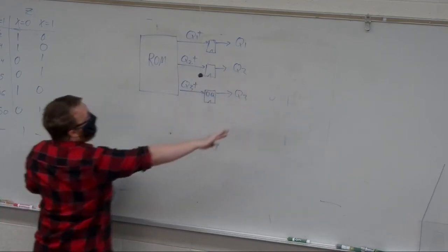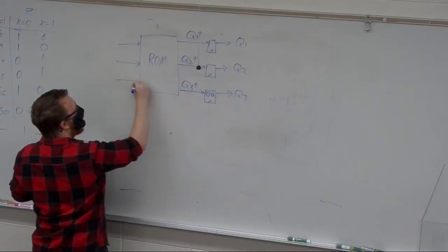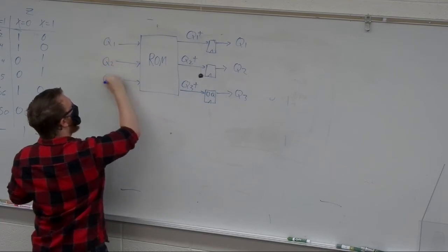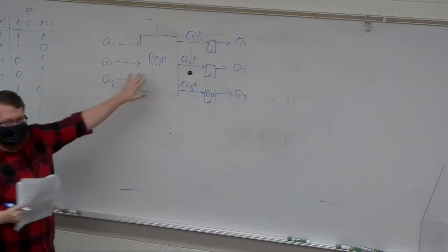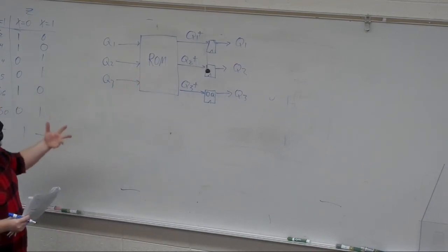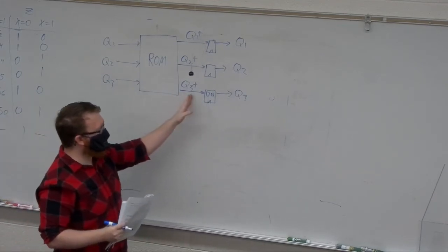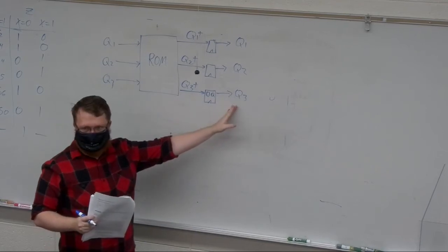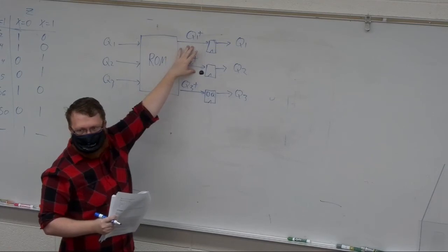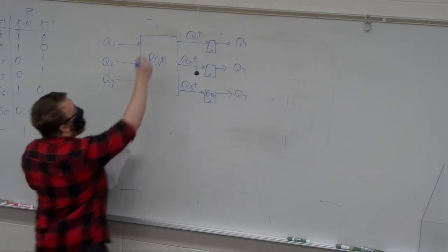So these are all going to feed back around as the inputs to the ROM. Okay? And so what that's going to do is on a clock, it's going to load the next state into present state, right? So as long as the lookup table is outputting the right values for the next state, we're good.